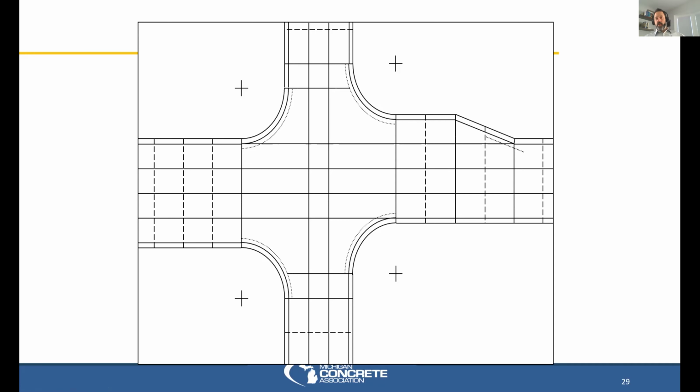And then after that, we measure in between those transverse joints that we've already started away from the intersection area to see what our maximum joint spacing is and whether or not we need a joint in those areas. So between our fixed points, we know we need 2 slabs here based on this distance. So we'll put 1 joint in. And let's say our maximum joint spacing in this example is 14 feet. Those may be 2 13-foot slabs. They may be 2 12-foot slabs, 2 12.8-foot slabs, whatever it is. And so the issue there is just divide it equally.